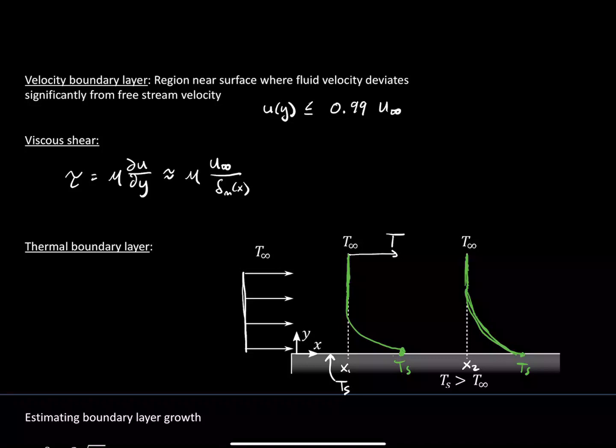So if we draw a boundary layer for this, a thermal boundary layer, that thermal boundary layer is going to intersect here and it's going to intersect here. So very much like the velocity boundary layer, you get this initial growth and then it sort of stagnates. It will always continue to grow in this direction unless something changes about the problem. Just like in a semi-infinite wall, that thermal wave will always continue to propagate. Right? It does so more slowly over time.